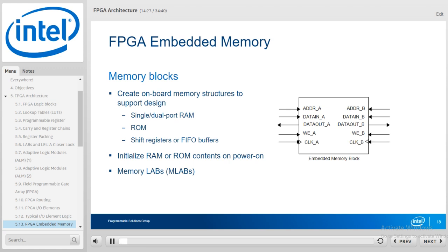Modern FPGA devices contain specialized hardware blocks in addition to LABs. These dedicated resource blocks take up one or more blocks in the array and are completely accessible through the FPGA routing channels. Often these specialized resources are arranged in a particular row or column of the blocks in the device.